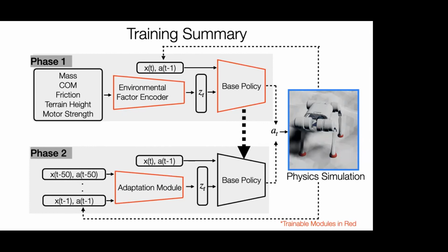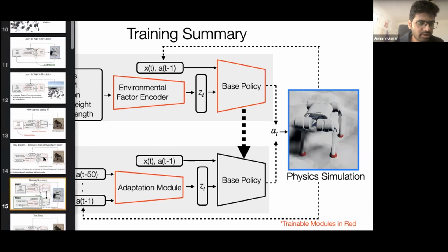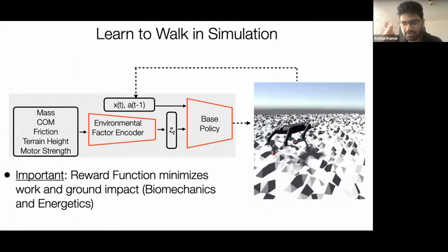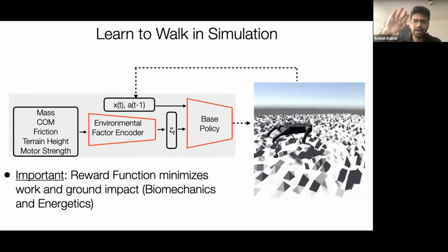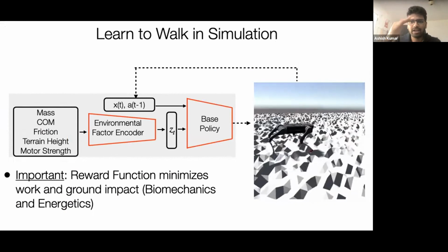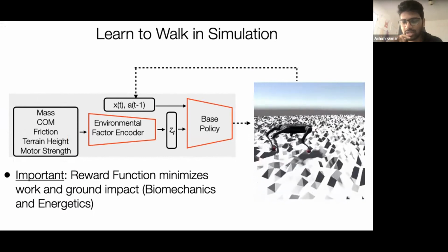Thank you. Just a final follow-up clarification question. What's the reward function you used in this project? I don't think you mentioned. So we have the task rewards. The robot has to move forward at a particular speed. The robot should maintain its orientation as upright, and it should not have any yaw in the sideways direction. So it should be walking forward in an upright position. Those are the task rewards.